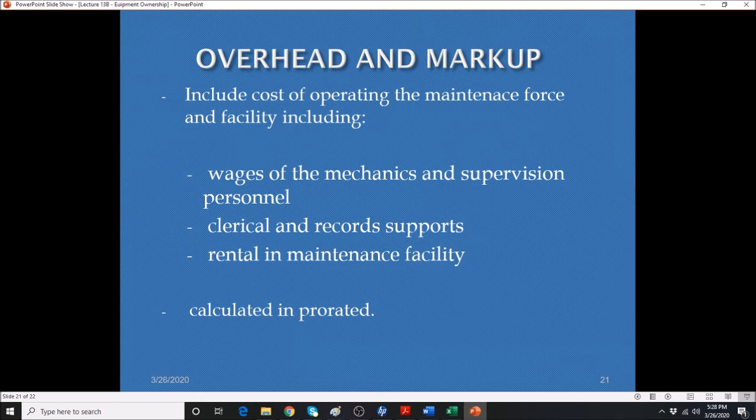Overhead, as you've probably learned in your estimating course, can be either project overhead. Those are the overhead costs that are directly associated with that particular project. And we have the office overhead costs. Those are back at the office and support the operations of your company. In the case of project overhead costs, those are your job trailers, security fences, and utilities on the job site.